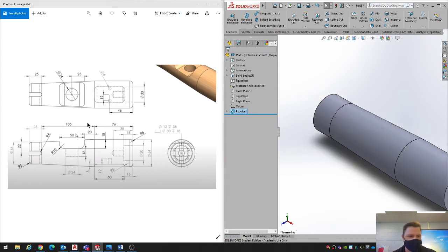Alright, now let's look at the back. So I'm going to try to do some fillets, and then the rest is just cutting stuff out of this shape. Like this is a cut here. It also happens on the top. You can't see it, but it happens both directions. This is a cutout. This is a cutout. This is we're going to use the hole wizard to get that. Then I'm going to cut this out and then this out.